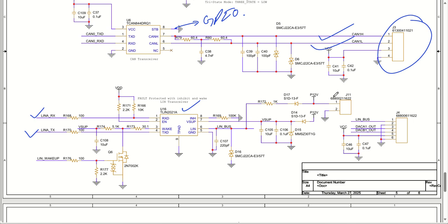It is pulled up. Okay. And the power supply that you want, you can give it from here. So one connector is provided here to give a 12 volt power supply, up to 20 volt, 24 volt also you can give, not a problem. And this particular pin is going to go to my supply pin that is there, 12 volt with ESD protection and diode protection circuits with capacitances.